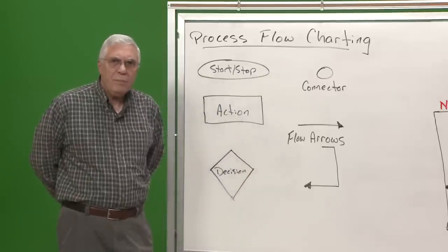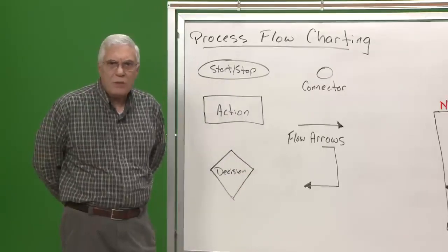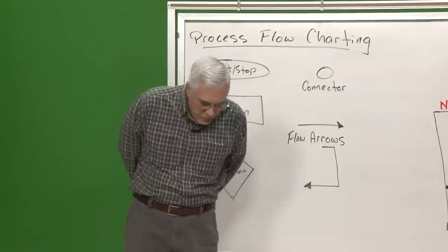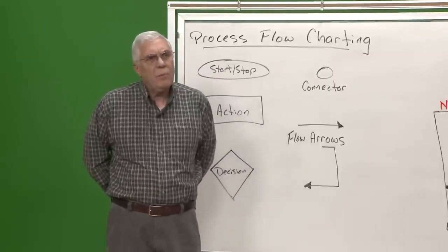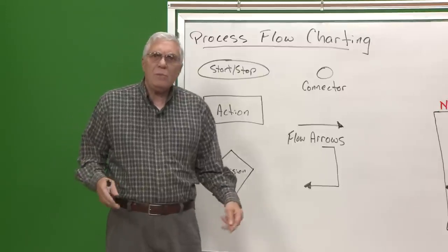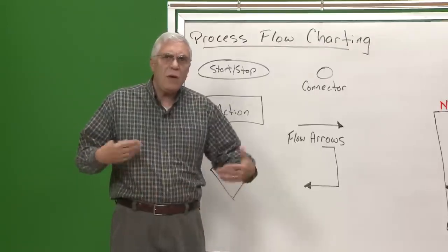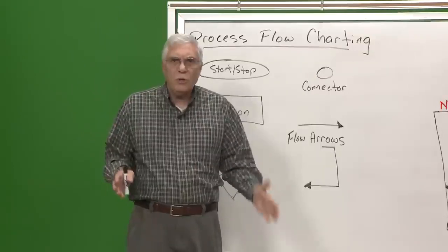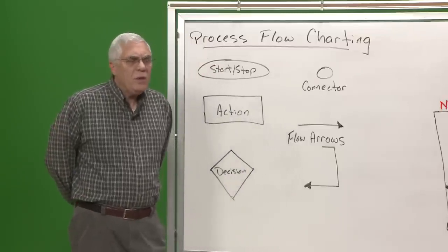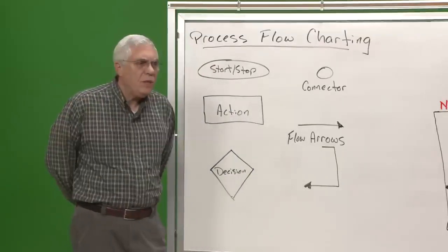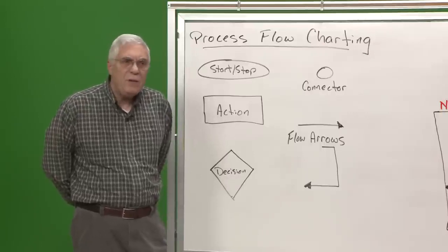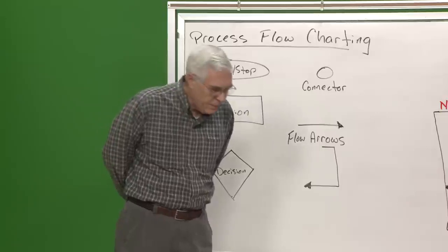Actually, what we're monitoring is the variation present in the process, and every process has variation in it. It always happens a little bit differently. That variation can represent what we often call common variation, which means simply variation that comes out of the nature of the process. The way we've decided to do it is going to create a certain amount of variation. Assignable variation within a process represents that something's gone wrong. Something within the process is not happening the way we meant it to happen or designed it to happen, and we need to track that down and correct it.